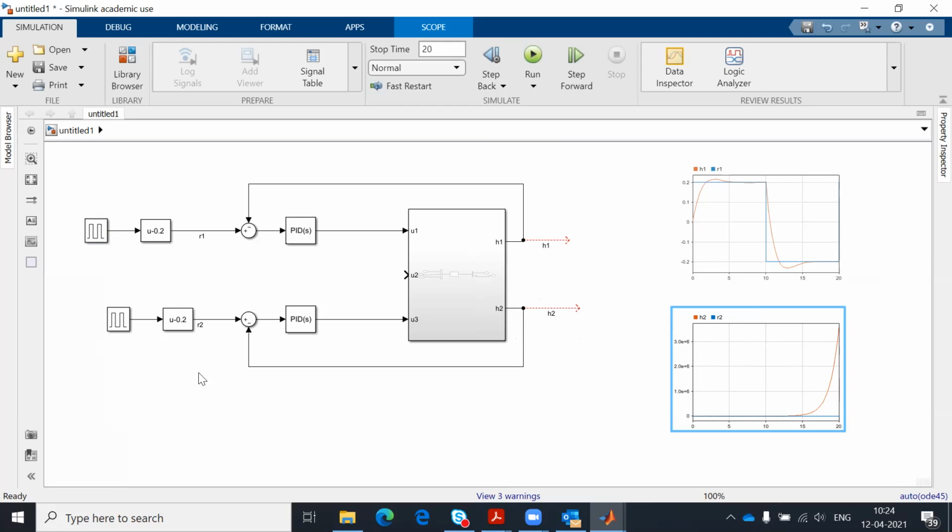But if you think about the first system, I'm pointing to the figure. When the level of the first tank is less than the set point for the first tank, you should open the first valve. But it's the opposite for the third valve, because the third valve is at the output, not at the input. Does that make sense? So the controller you design for the third valve is not the same as for the first valve. What to do? Any idea?